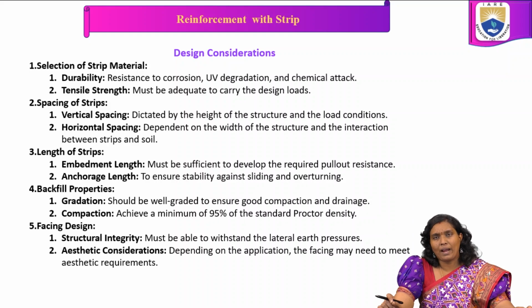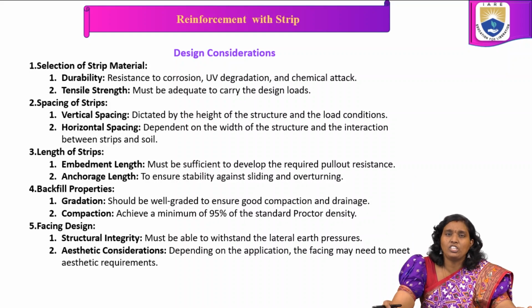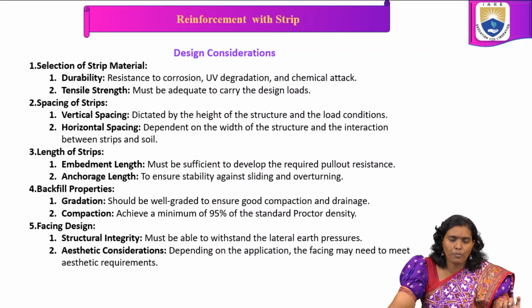Abutment length must be sufficient to develop the required pull-out resistance, and anchorage length to ensure stability against sliding and overturning. In backfill properties, gradation and compaction are the parameters considered.